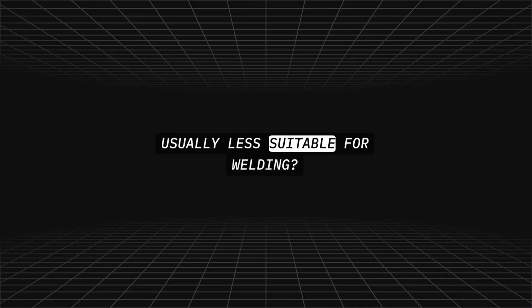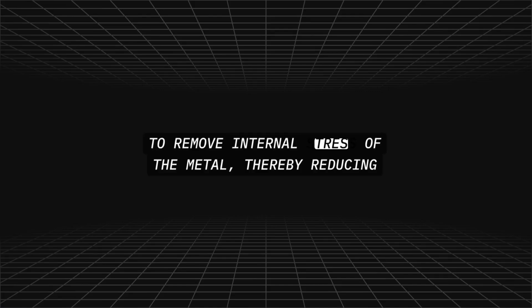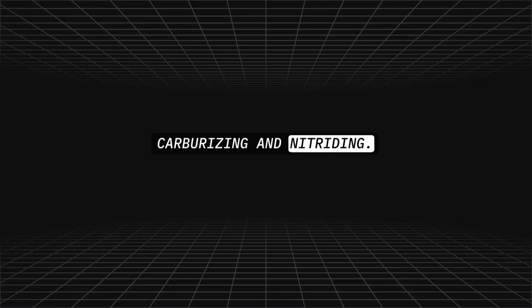Why is alloy steel that is responsive to heat treatment usually less suitable for welding? Because of its tendency to become brittle and lose its ductility around the weld. Why should steel be normalized after welding or machining? To remove internal stress of the metal, thereby reducing brittleness. What are two methods of case hardening? Carburizing and nitriding.